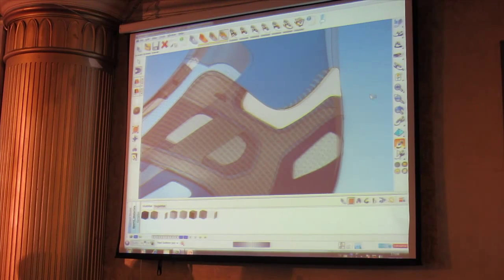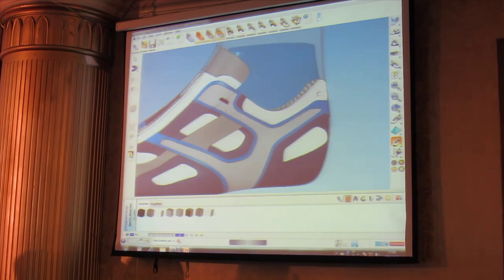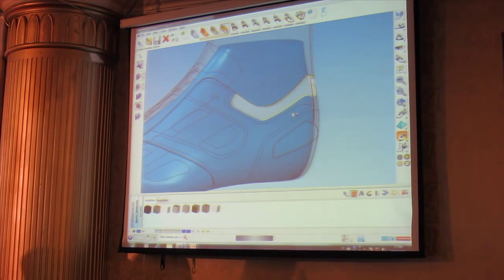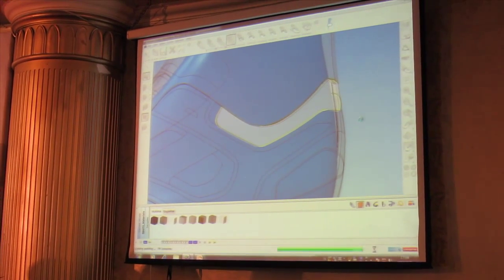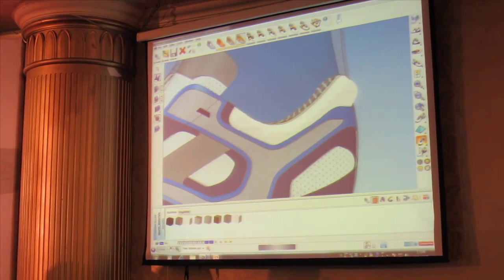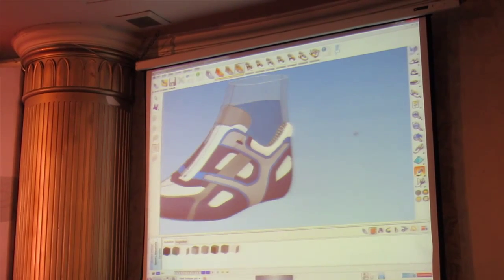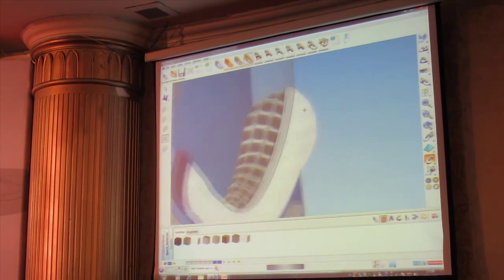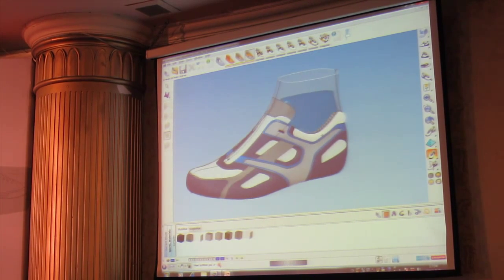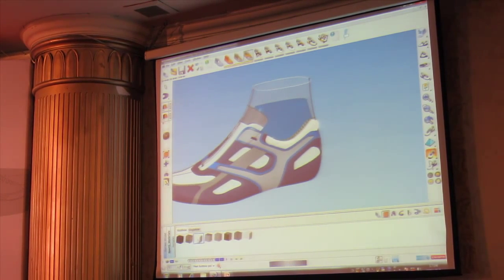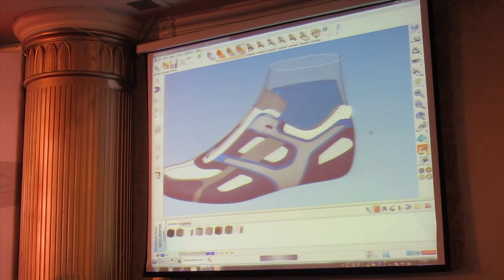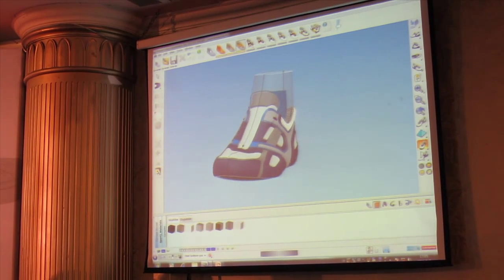So again, I can use the single click method to create that piece. And once that's created, we can apply different effects to the pieces. So in this case here, I'm going to convert this into a padded piece. So I'm now reselecting the piece and we'll apply a padding effect to it, which you can see there. If I now look from the side, you can see the bulging effect that we've applied to simulate padding of this part. And again, come to the materials and I'll drag and drop the material onto the part itself.